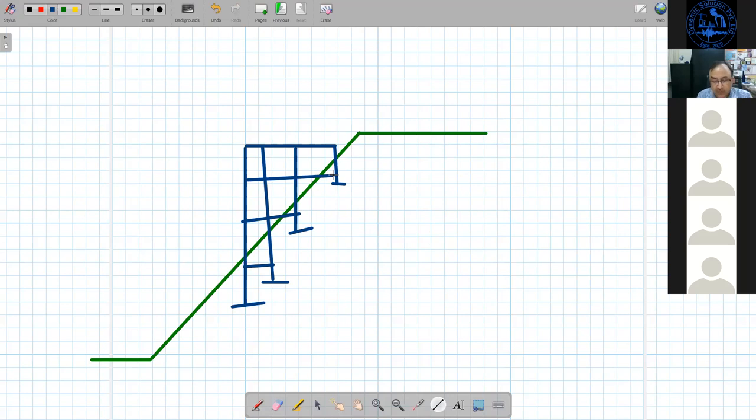First of all, the bearing capacity here: when the failure occurs, it will occur on one side. We have a Terzaghi wedge failure. This wedge failure occurs on one side. It cannot fail to this side. So the bearing capacity is low.